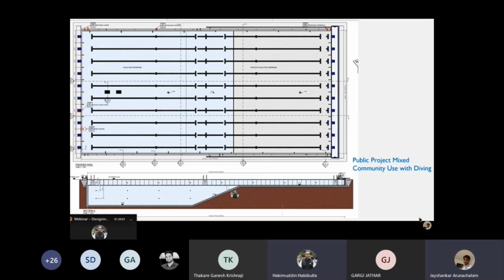And again, because it's a very steep drop, we had to pay attention and provide a break point at a stage where you can park the bulkhead, so that accidentally nobody goes into the deeper end of the pool or loses their footing and panics. So this will come here, and then it gets parked. The first stop for the bulkhead is around the 20-meter mark, and then the second stop is at the 25-meter mark.